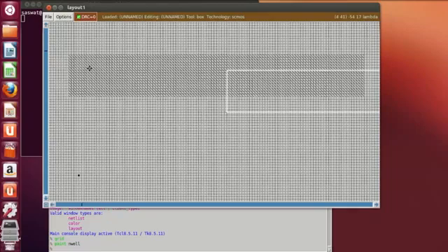Now before drawing the p-well, we have to keep in mind the function is (A plus B) dot C. So when we have a plus operator, the NMOS will be in parallel and the PMOS will be in series. And when it's (A plus B) dot C, then the C input will be given in series in the case of the NMOS and in parallel in the case of PMOS.